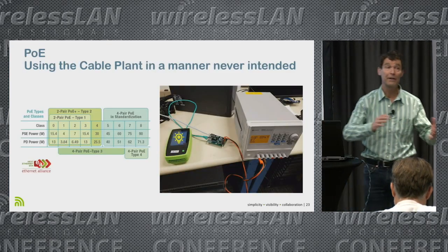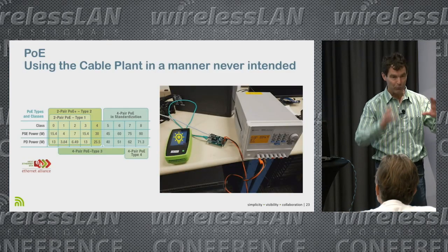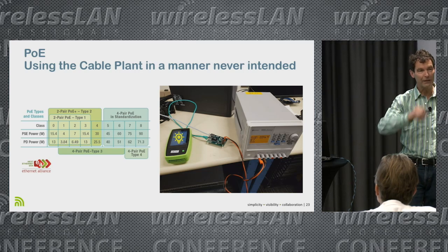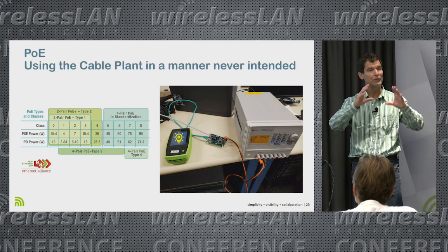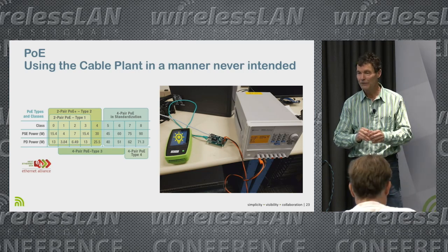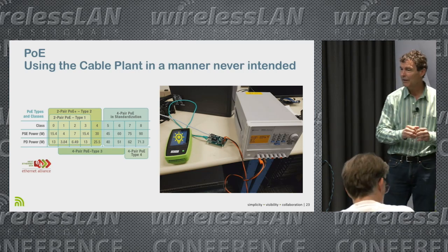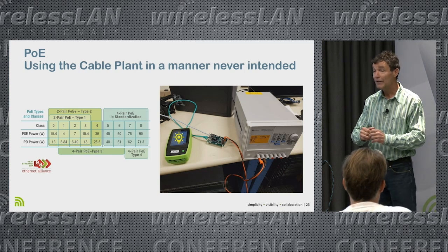So the other way is that the number of cables in the bundle will affect the amount of noise and crosstalk too. And I would imagine even the speeds of the cables in the bundle would probably have an effect. So I'm going to try to do more characterization on that going forward.